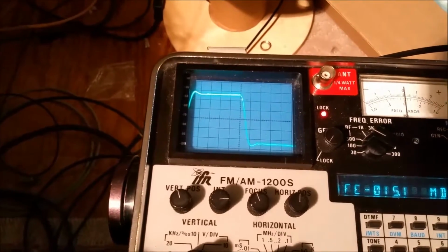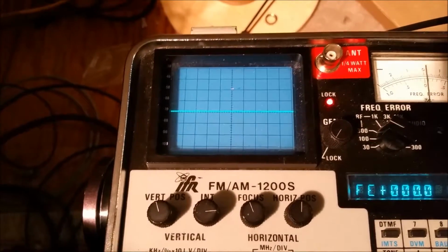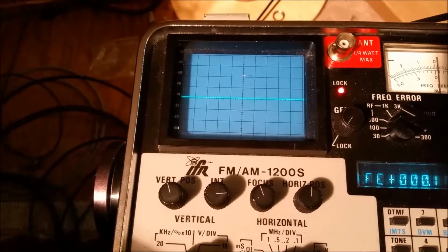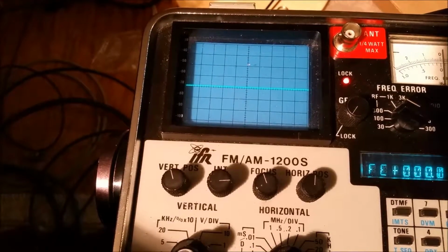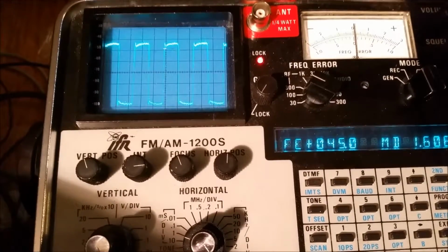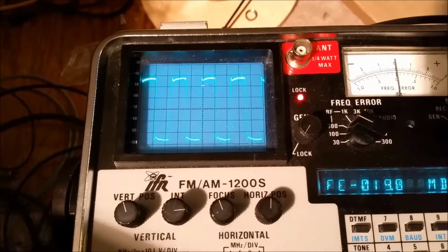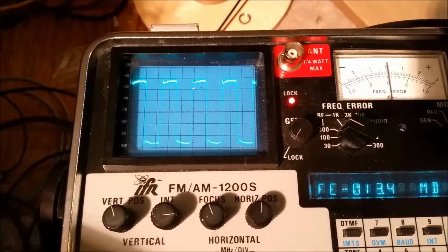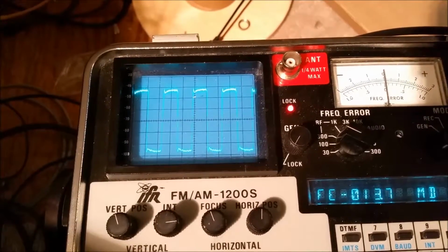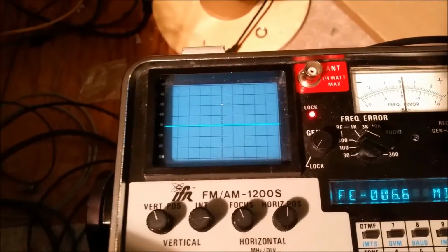One of my gold standards is the 400 hertz square wave. If you can pass a 400 hertz square wave through it, you can pass pretty much anything. So let's do that test here. So got a 400 hertz on the generator, and there it is. Like I said, it's got a little bit of a ring to it, but I tell you, that's a beautiful sight right there. Like I said, I think that ring's due to my probe. But there you go.